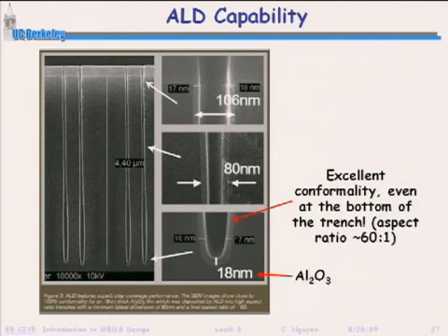What you have to do for a lot of those types of films is put down a very thin film of alumina first, maybe 3 nanometers. Then on the alumina, you'll get a very dense forest of the hydroxyl groups. Then the titanium dioxide can come in and form very well over that alumina. So there's some art in ALD. There's some ordering of layers that you want to put down to ensure the best films.